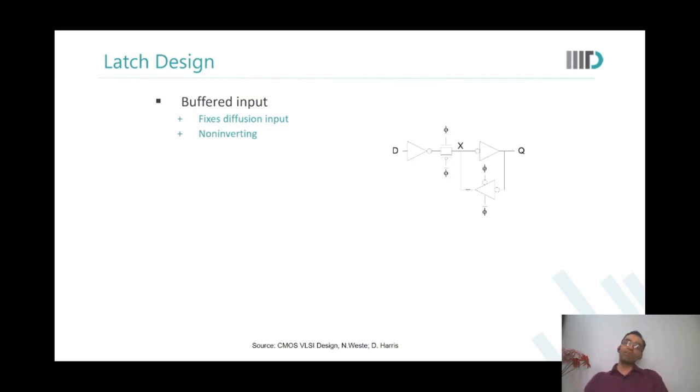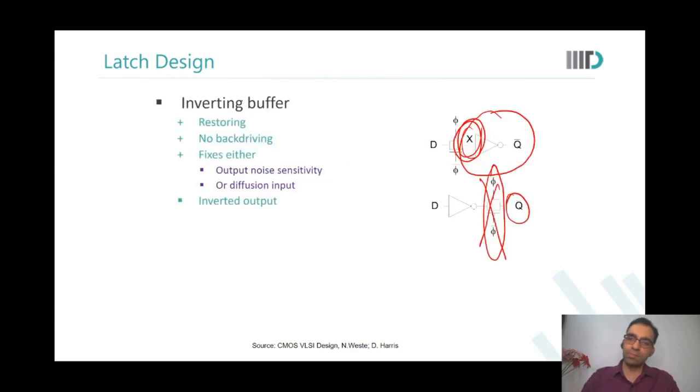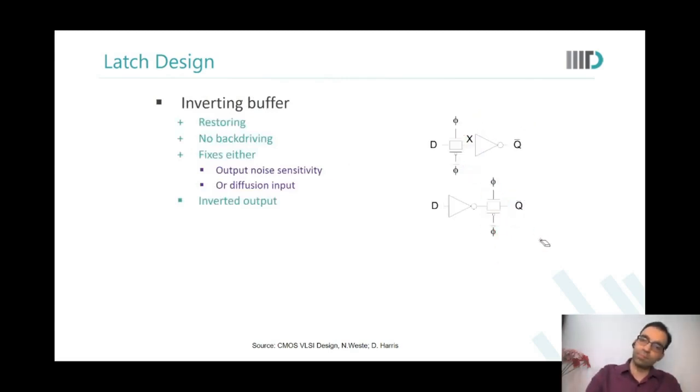So even when that one inverter was put, do you realize that there were nodes which were not driven when the clock was off? There were floating nodes there where the charge was stored on some gate or some capacitance. So if the inverter was at the output, after the transmission gate, then I won't be getting floating, right? The output is floating now, no? Here in the second one is floating, but the above one is not floating, right? Above one, X is floating. Okay, right. Therefore, output becomes floating.